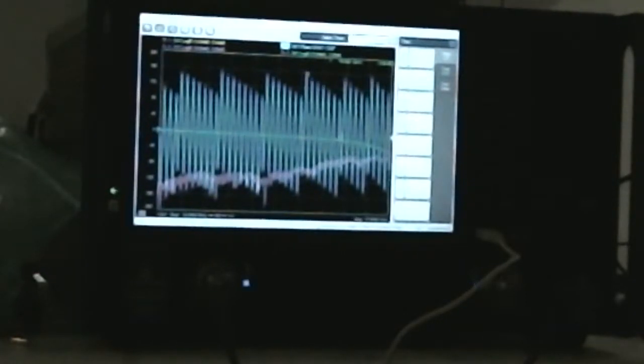It's not reliable, okay? So when we are looking into cable, we have to look at a parameter called phase stability. If somebody says they make a network analyzer cable, there's a couple of companies: a Japanese company called Junkosha that makes very good cables, and another company called Gore, out of the States, that makes very good cables as well.